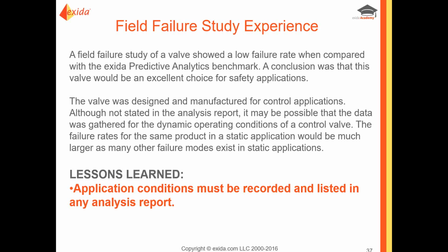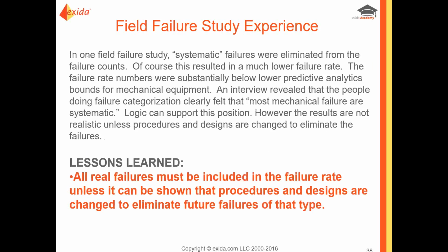If the valve, in fact, was static, there's a bunch of different failure modes that can occur when a valve is not moving that just do not occur when a valve is moving. So the failure rates for the same product in a static application would be much larger than that product in a dynamic application. Point: application conditions must be recorded.